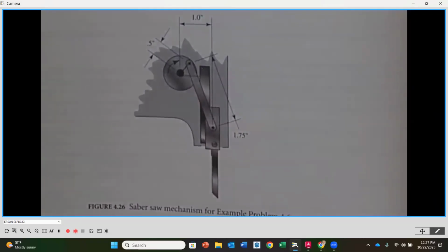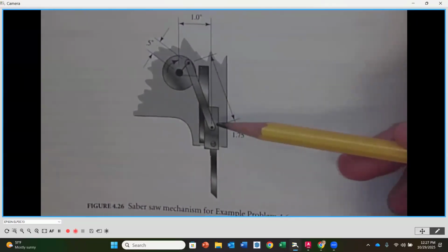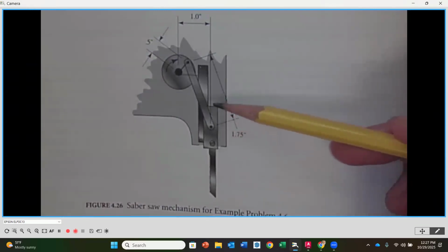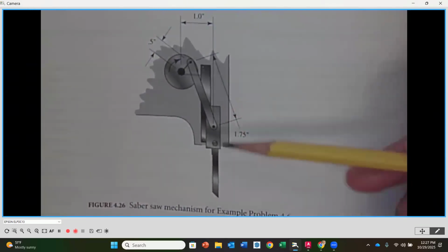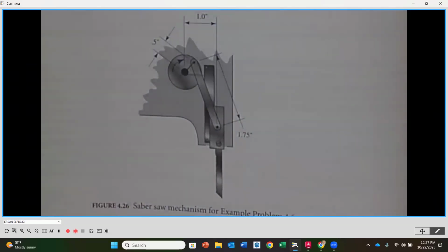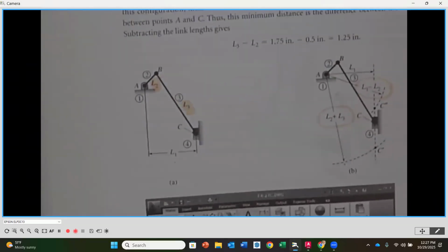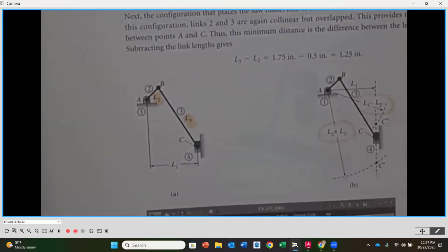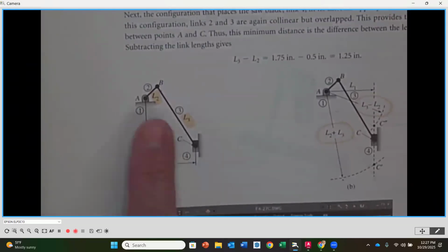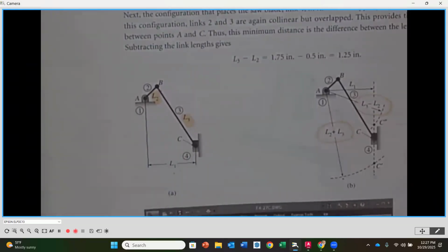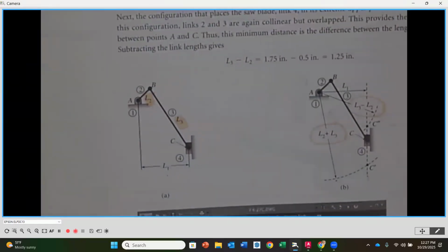And what we want to do is find what the limiting positions are for this mechanism. So we want to find out how far this blade is going to go down, and how far up it is going to be. What are the extreme positions, the limiting positions? Now, to do that, as you can see over here, this is the kinematic diagram, which is reflected in the one that we drew in AutoCAD. Their frame and slider are a little bit smaller, so proportionally it might not look exactly the same, but it's really just the placement of those points, so it's totally fine.